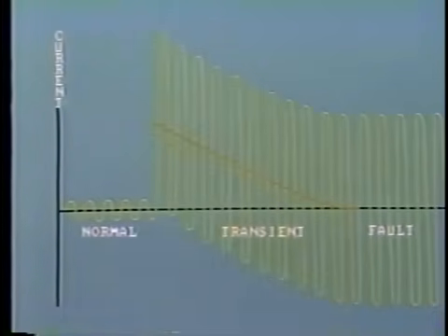And here we see the same sine wave, but with much greater amplitude due to the fault on the line. Indeed, this may be high enough to cause saturation of the CT's iron core. However, there is yet another factor to make matters worse. Between normal current flow and stable fault current flow, a transient is created like this for perhaps 15 to 20 cycles.